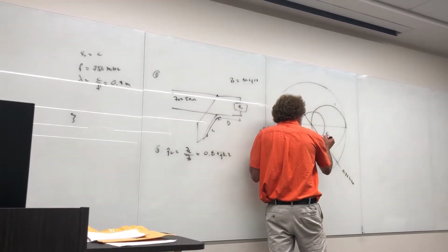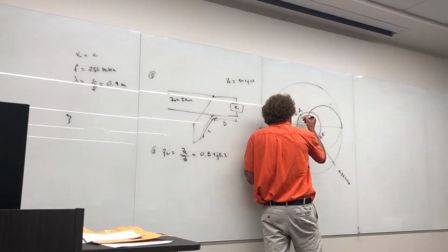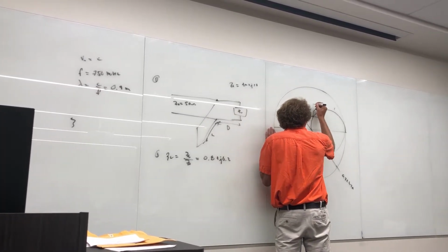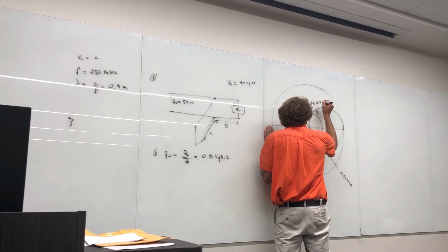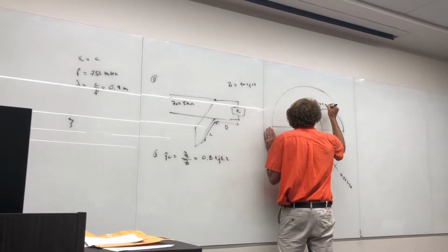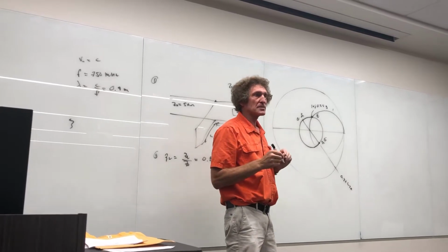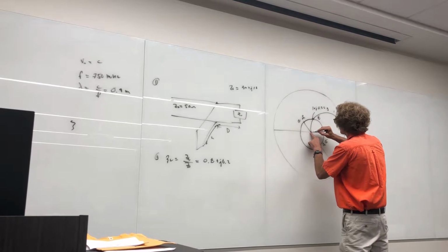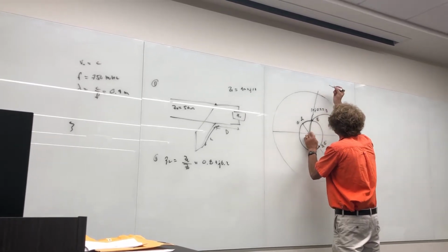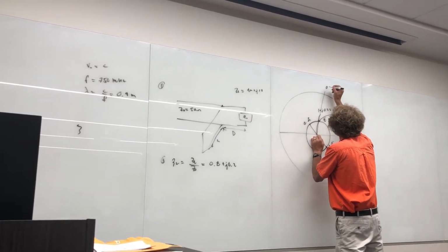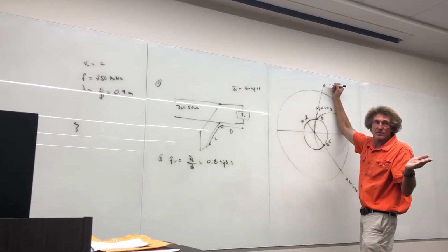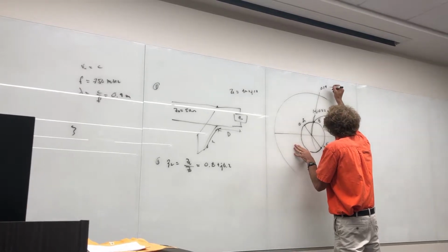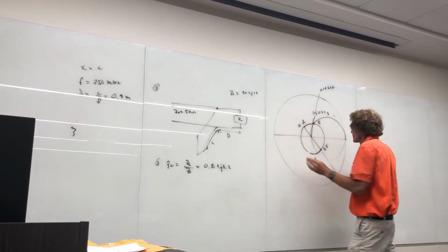Now we have to move from here all the way to the one circle. This would be 0.3 right here. And this will have a value of 1 plus J 0.3 approximately. Remember, that's Y. Does everybody see that point, class? Now when you have that, you've got to throw another line straight through here. And you're going to come towards, I think it's 1.4 wavelengths towards generator. Yeah, 1.4 wavelengths towards generator. Remember, those are fractions of wavelengths.